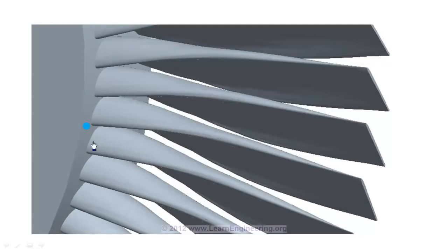When high-energy steam at inlet, the steam with high pressure and temperature, flows over such a blade, it will induce a pressure above and below the blade. And thanks to the special shape of the blade, the pressure above will always be less than the pressure below. So, there will be a resultant net force acting in the upward direction. This force will make the blade rotate, in this manner. As the blade rotates, it obviously absorbs some energy from the fluid, so fluid at exit will have less energy compared to inlet. In the coming session we will see how we can predict the energy transfer in the fluid.